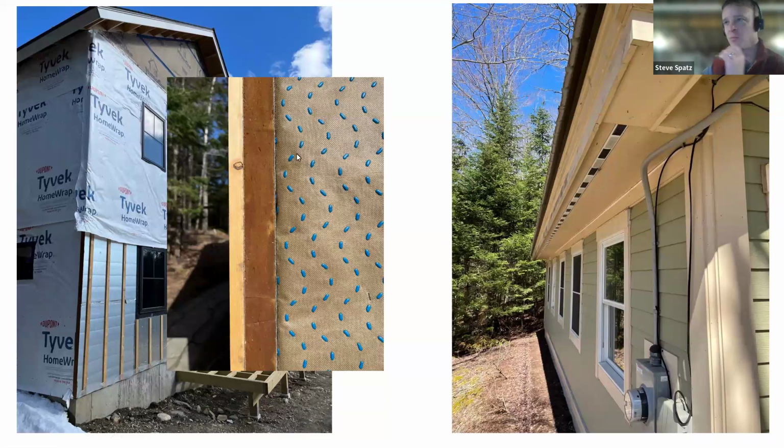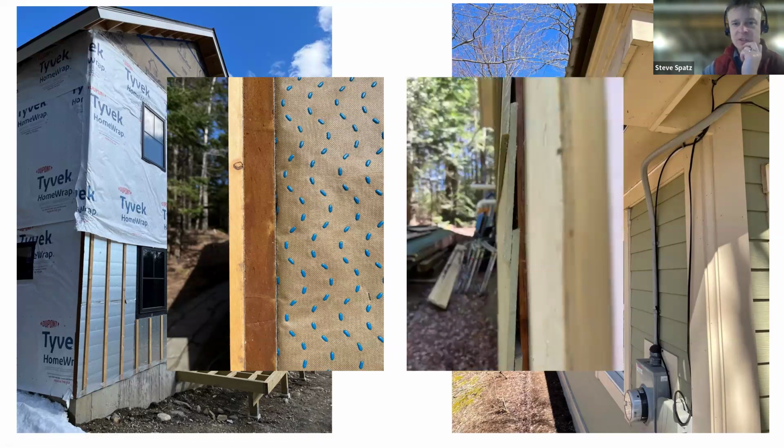We don't need a physical break as much with the 1x3 strapping as you see here, as just an ability for moisture that's coming through the assembly behind it to diffuse outward. So you don't have to make it robust, quote unquote, physically to create that pathway for vapor transport from the wall assembly to the outside to dry. Even just 3/8 strapping ripped behind the siding is enough of a disconnect between the assembly behind it to allow for that drying to occur.